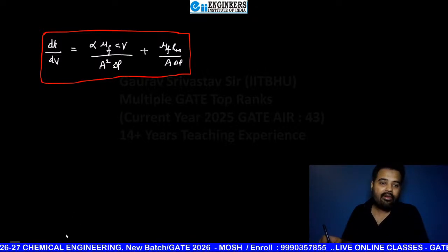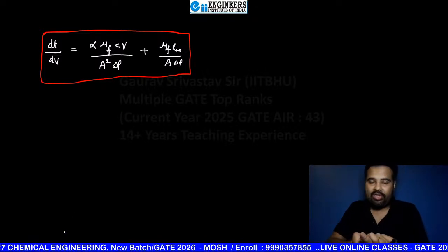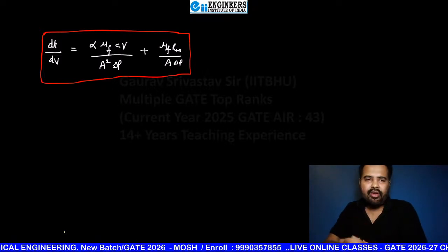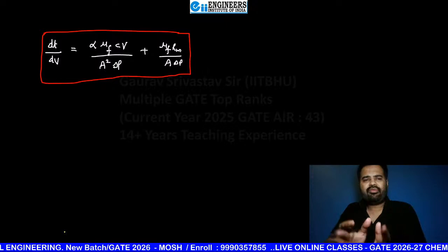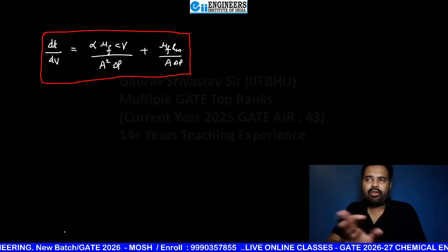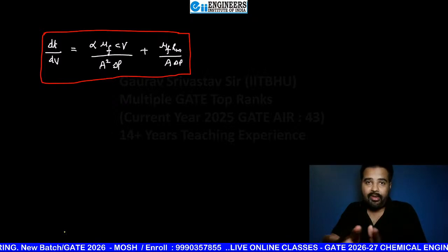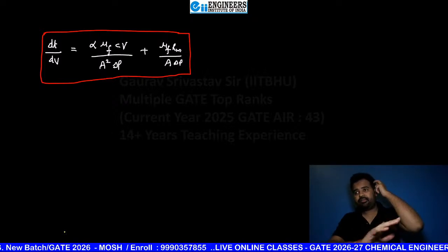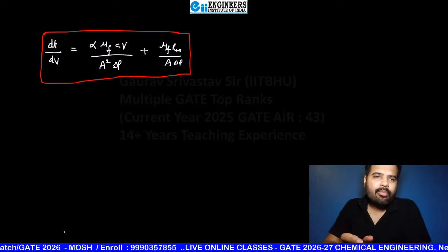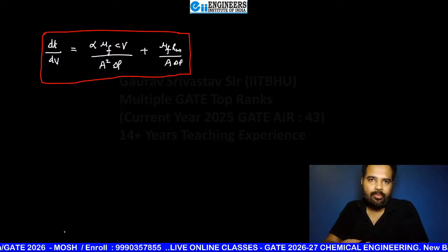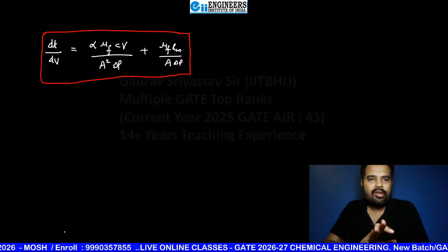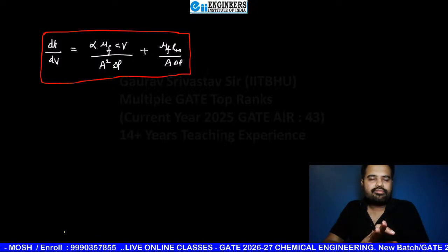Now, when they are asking any question in an examination, suppose they tell us that delta P is constant, that is, the pressure drop you are not going to allow to vary. Even if the cake thickness increases, the pressure drop is managed somehow as a constant value. Pressure drop constant: constant pressure filtration.